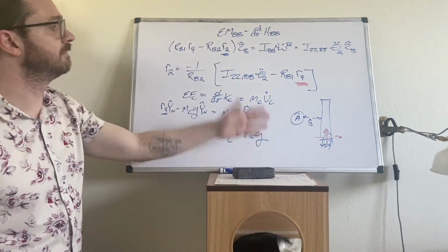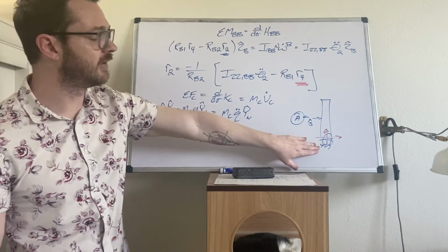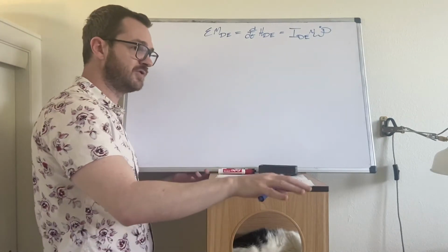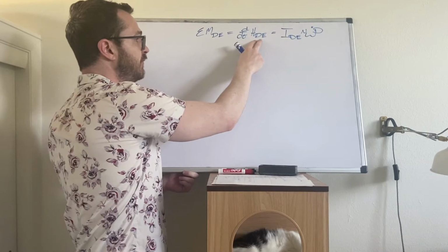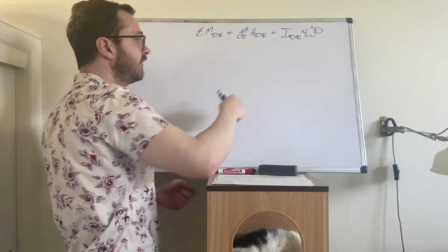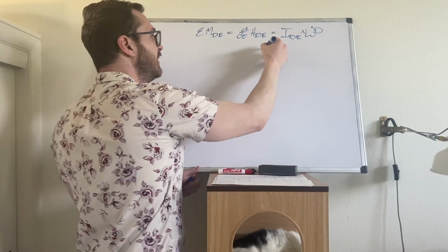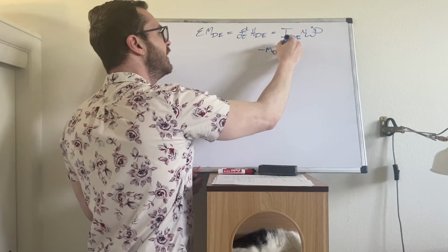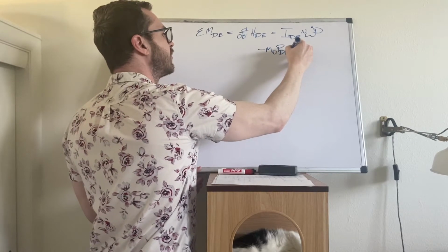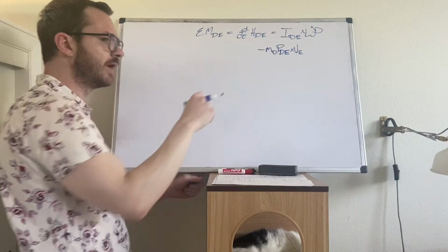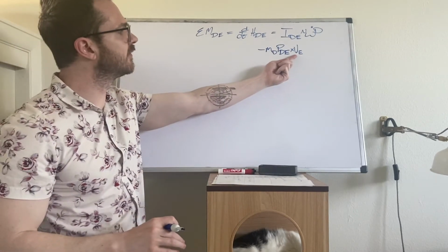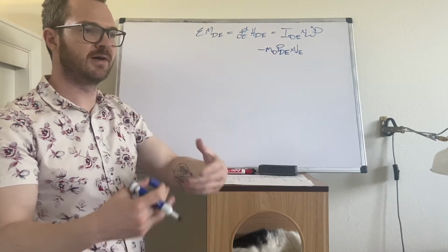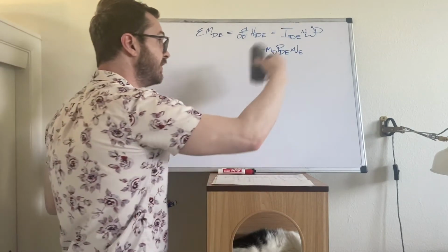Okay, let me clean this up, and we're going to get started on body D. Euler's second law on body D. I've done some major simplifications. We know that if we're doing angular momentum about an arbitrary point, first of all, there's an additional term that you need to add into the angular momentum term, minus md p d to e cross ve. Don't ever forget about that term. Conveniently in this problem, we're taking the moments and the momentum about point E, which doesn't move, has no velocity. So this term goes to 0.